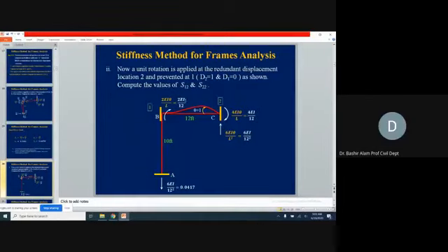At the far end, 2EI, and the balancing couple again here downward. Why downward? Because the unbalanced couple was clockwise, so the balanced couple should be counterclockwise. So this should be down, and this should be upward direction. So 6EI theta over L square. These are becoming the reactions.